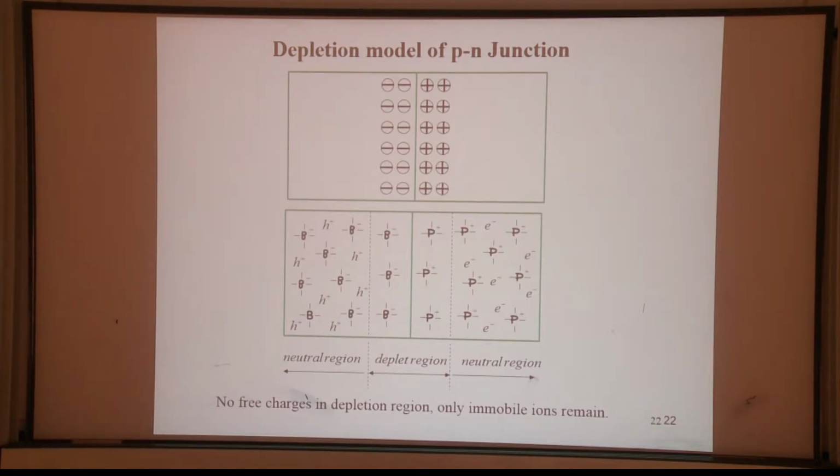of p-n junction. Actually, here is neutral. Even though we did the N-type doping, it's still neutral. Even though we create electron mobile charges, it's still neutral. It becomes positively charged when the electrons diffuse to the other side and expose the immobile charges. Then it becomes not neutral.